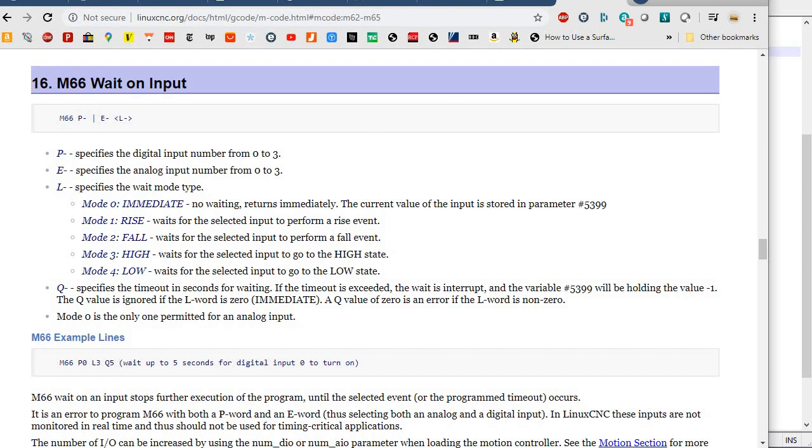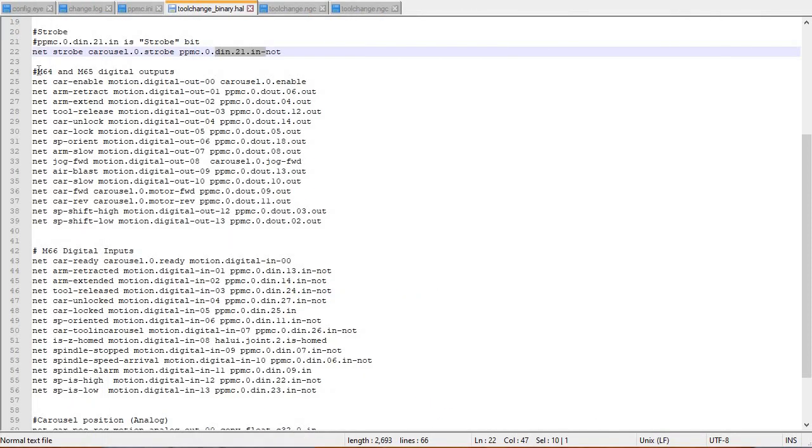That's the Q5, right? So when you actually want to talk to your hardware, the way you do it is you say M64, M65, but it has to know what M64 and what M65 to talk to. So I defined all these things. I have carousel enable, this is an output. There's basically a line that you need to light high, and this is a virtual line, by the way, to tell the carousel to actually move. And then I've got these physical outputs.